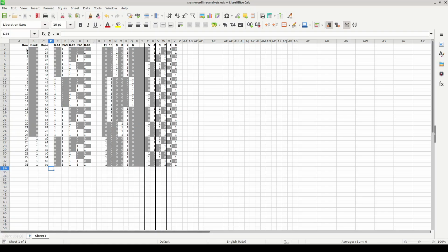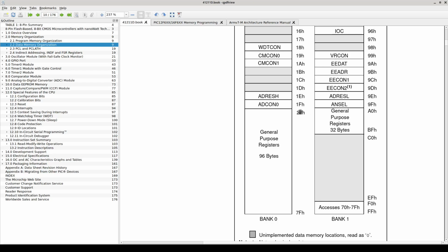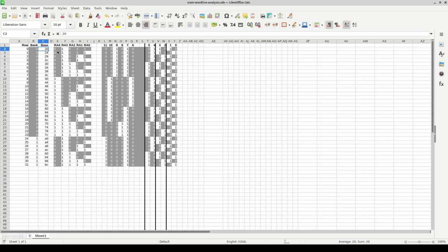So I went back to my spreadsheet and I plotted out this address map and assumed that the top of the array was the first address in the logical memory map. So in this case, we're at 0x20 of bank 0. And then going over here, again remembering that we do have 4-byte rows because of the column mux, 0xBC is going to be the highest addressed word line in bank 1. And so if we plot this out and we look at what the actual address bits of these addresses are, so looking at the bank ID followed by here, it's a nearly perfect match. And so now everything starts to fall into place.